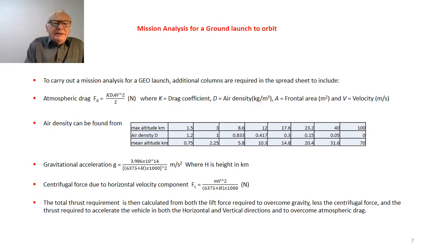The idea is you aim to calculate the total thrust requirement from both the lift force required to overcome gravity, less the centrifugal force, and also the thrust required to accelerate the vehicle in both the horizontal and vertical directions and to overcome atmospheric drag. So it becomes a rather more complex spreadsheet.